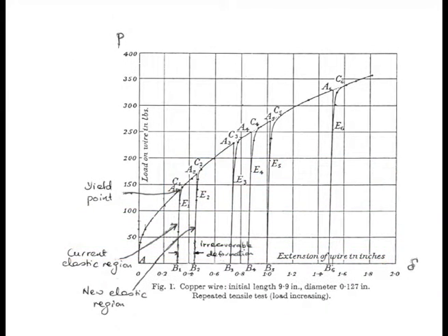You look at a copper wire, it's the same thing. Let's take a big one, right at the top. When you unload this, you look at this line, there's a bit of a rebound. So from A5 to B5, there's a small amount of elastic rebound. But the big one is obviously this one. And the total is this plus the small amount here. Am I correct? So the idea is that total strain is equal to the sum of the elastic and the plastic component. Is that alright?